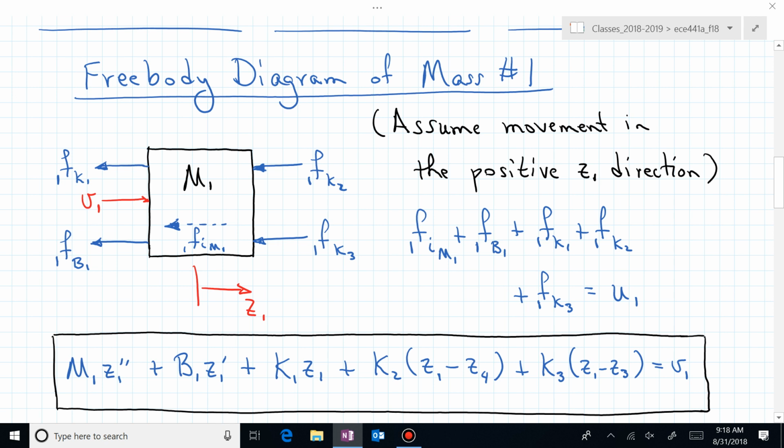That's the inertia of the mass that's trying to resist movement in the positive z sub 1 direction. That's why it's directed to the left. We clear on the inertial force? Now if I say inertial force, you're going to be thinking elephant, aren't you? That's okay. At least you start remembering directions, maybe.